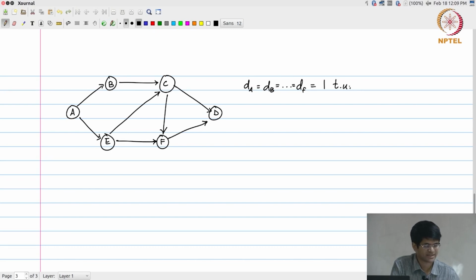Each of those hardware units essentially takes this 1 time unit to execute its particular function. You can even think of these as combinational gates, AND gates, OR gates if you want to. Therefore, if I now ask the question, if I consider this entire system as 1 unit, what is the critical path and therefore the best iteration period that I can get for this implementation? What would you say is the critical path through this circuit? How many time units? Shout one number. What is the critical path?